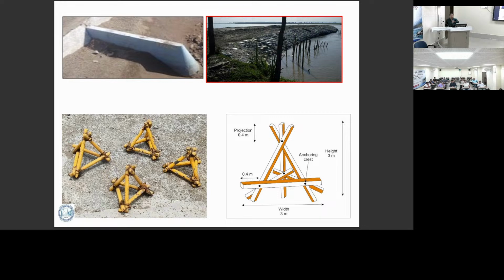That I told you how to convert it. So you put a discharge. For the particular discharge, there should be a gauging station downstream. You have to control for that one. So you have to ask the project to give the gauge discharge curve at the area of interest. So you maintain that downstream and you will get the water levels. That water level should be checked against the prototype value. At one or two locations they will have water level for a particular discharge. If those match, then your model is calibrated.